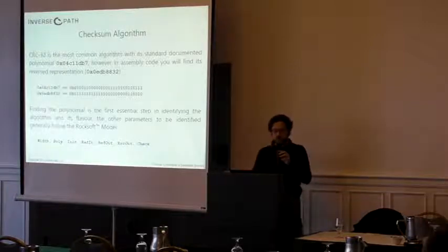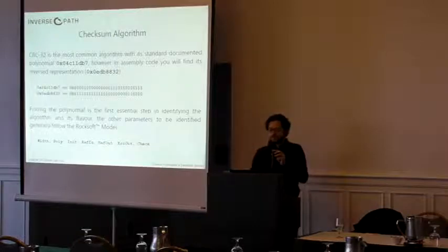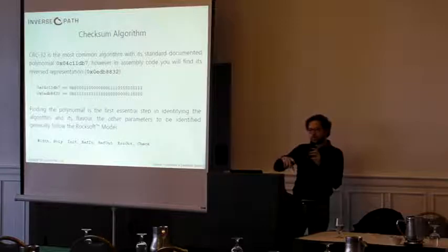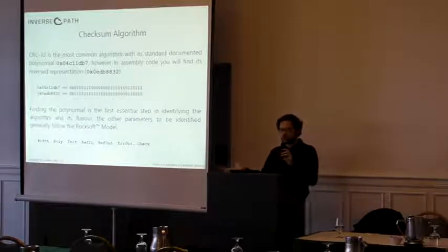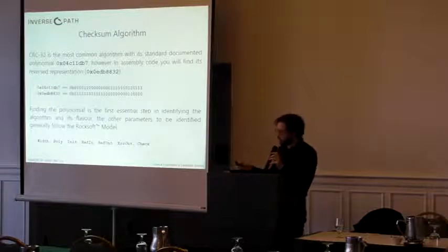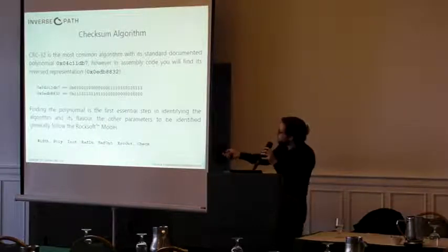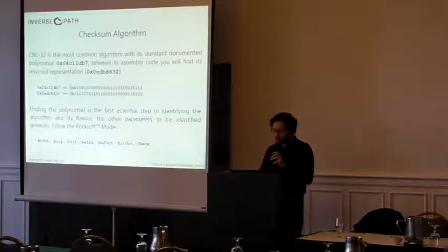It's well documented. It has a polynomial which is used for the computation of the algorithm. However, we have to be careful if we want to find that polynomial in the firmware code that you extracted. You will always have to check for its reverse representation. So even if you have documentation that says the polynomial is 04C11DB7, you have to actually look for EDB88320.